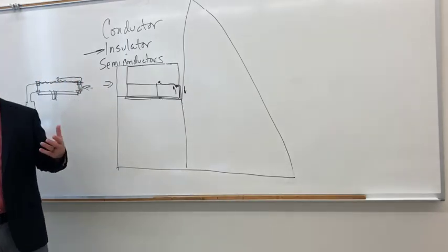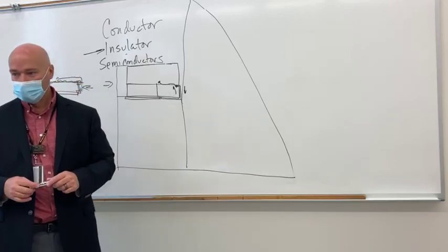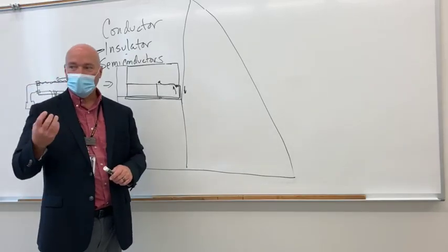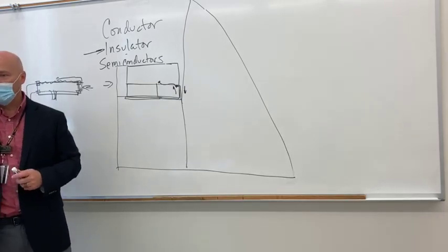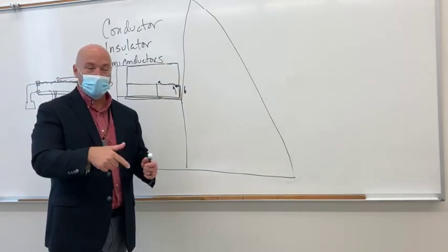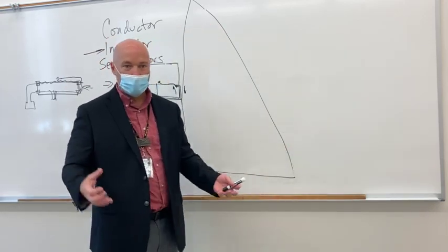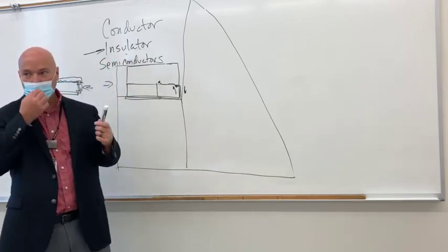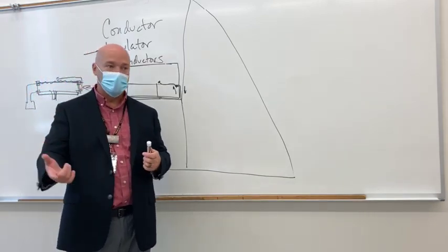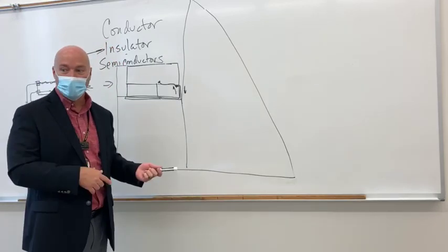So you take distilled water and you stick your hand in it. Is it still pure? No. What's on your skin? Germs, sweat, oils, right? Even if you were standing in a bucket of distilled water and thought, distilled water is a good insulator, I'm protected, no, you introduced impurities that make it a very efficient conductor.